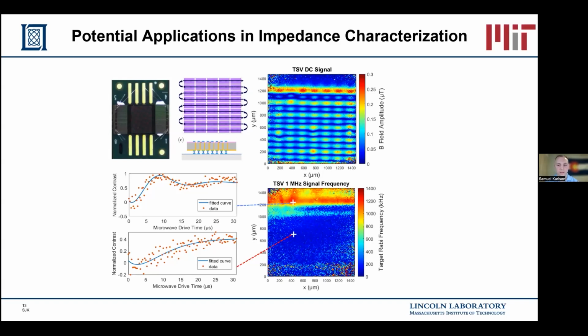After evaluating the device on a network analyzer, we concluded that the chip likely had some capacitive or inductive characteristic preventing us from seeing the structure, likely some capacitive short that caused the input signal to traverse a different path through the TSV chip. In the upper right, we see the absolute value of the magnetic field for a DC signal compared to the detected Rabi frequencies at AC frequencies below it, with the Rabi oscillations for 2 of the pixels for our AC frequencies.